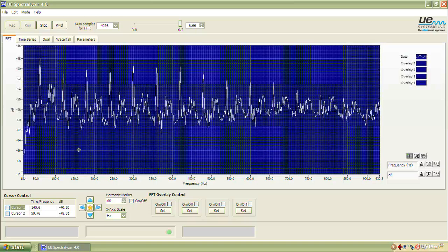Now say I didn't know that it was that, and let's say we had a fault known at 120. Let's see if it lines up on 120. I could simply hit 120 in there and turn on 120. Well, there it pops up. I do have a harmonic there, but there's one at every half, so it's probably 60 like I first thought.